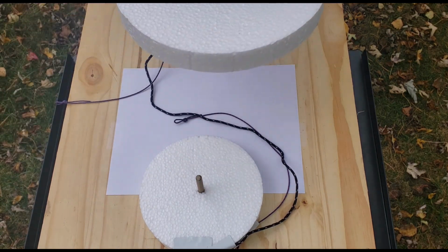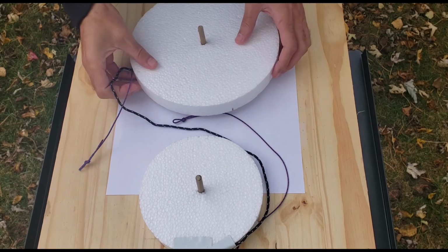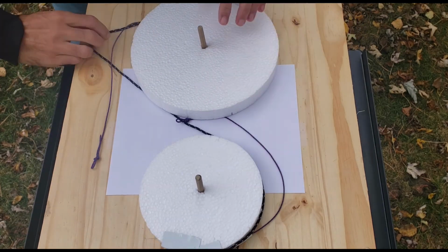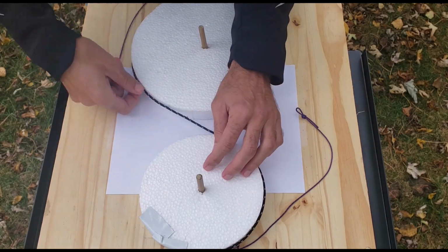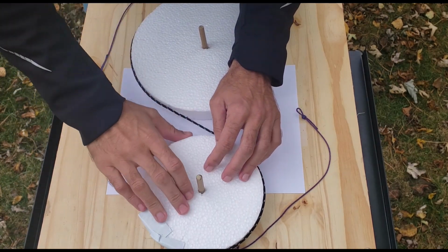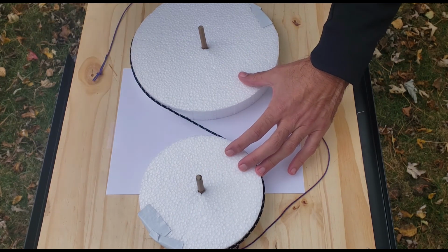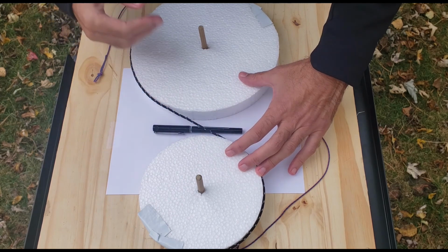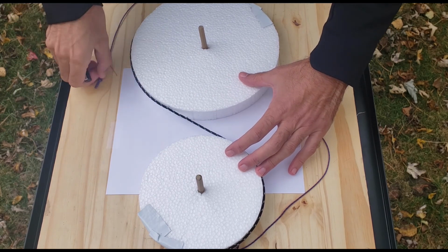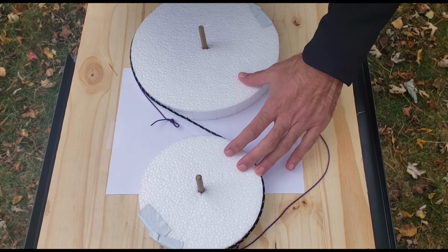Putting these back on their shafts so they can rotate. Tightening up this string that connects the two gears, and this does a great job of helping us to visualize where the pressure line is between these two base gears. And then here is the pen that's representing a line that's perpendicular to the center line. Okay, let's actually start constructing tooth geometry.